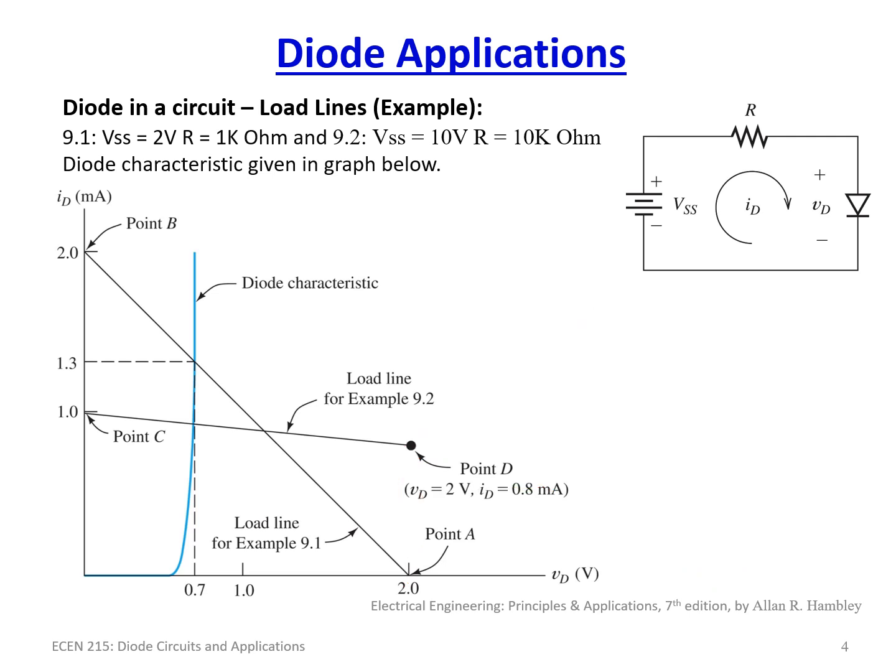Again, the relationship here is that out here it's at 10 volts, this line will eventually intersect at 0 milliamps. And then of course here we have VSS over R, which is 10 volts over 10K, which is 1 milliamp. So we have our point here.